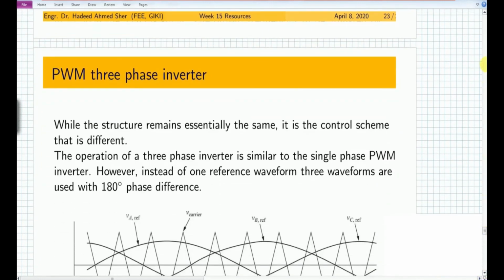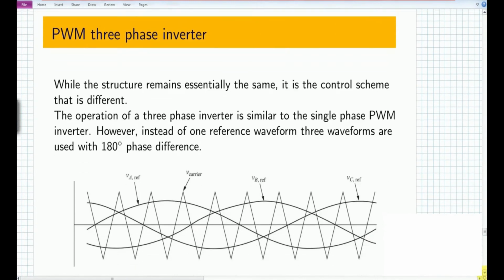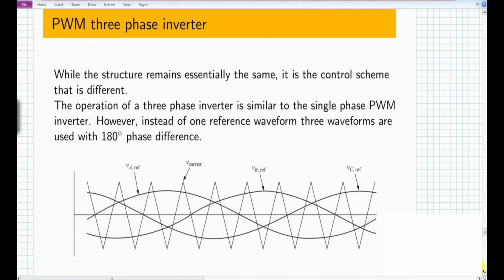Well, this three-phase inverter that we have studied so far actually has the same issues that we discussed for a quasi square wave inverter and for a square wave inverter. The foremost issue is not actually to get rid of the third or triple harmonics. The issue is to push the frequencies to a range which is a larger multiple of the fundamental frequency, so that the filter design is quite easy.